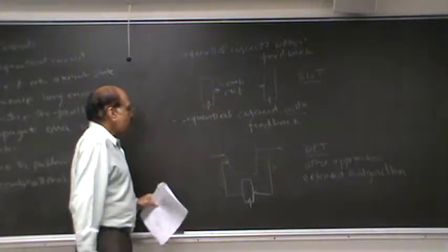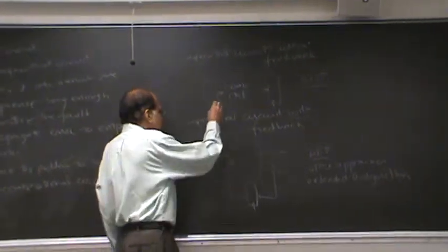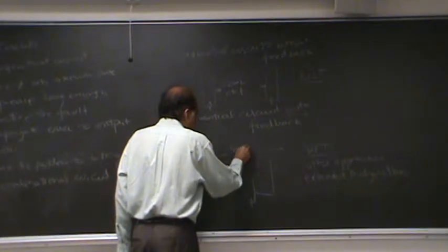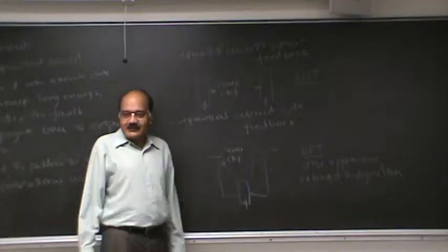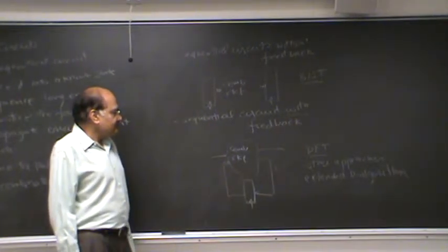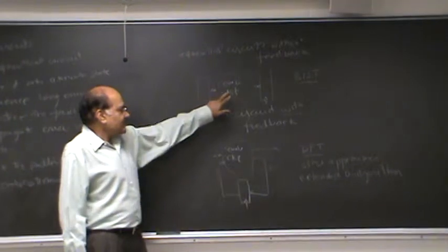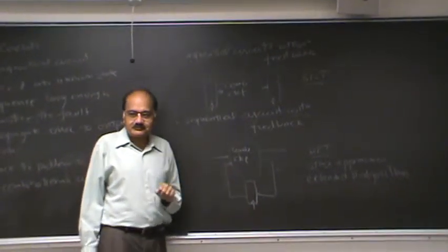And now we are going to assume that the faults, this is a combinational circuit, are only in the combinational circuit. Now, do you think that is a good assumption? So, in other words, we are going to assume that in storage elements there are no faults.